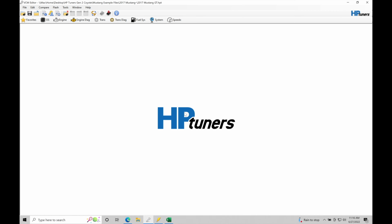The first thing I want to do is take a look at a calibration file, have one open up here so we can start to dig in to find the variable cam control feature in our calibration file. I have a 2017 Mustang GT calibration file open here. This is a manual transmission calibration file. I have a manual transmission specifically because the variable cam control scheduling modes has an extra mode for the manual transmission vehicles called manual launch. It's so we can take off from a stop much easier.